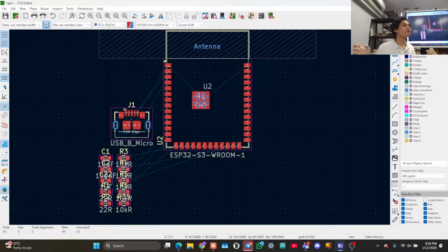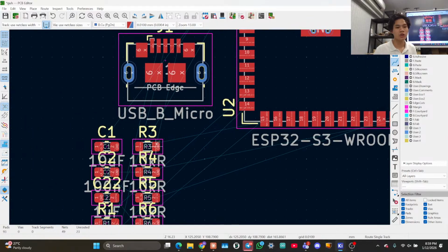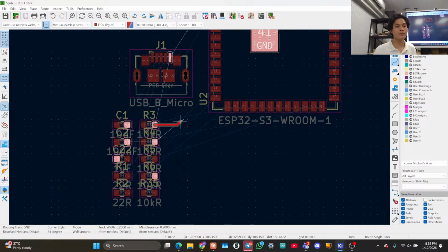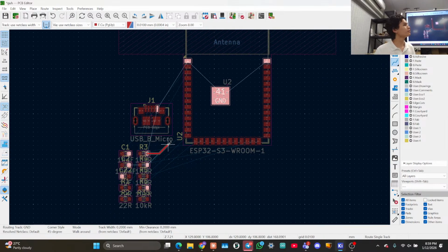For the purposes of layout, we call a wire a trace. We place a wire by going to this button here, Route Single Track. It's the 4th from the top, next to the layer count. These are real wires now, no longer ideal. Now I can place a track and look at my rat's nest. My rat's nest says what should connect to what. I'm just going to connect something like ground. Check it out. I clicked a ground pad, and now that I'm trying to put a trace, it highlights everything that belongs to the same net.